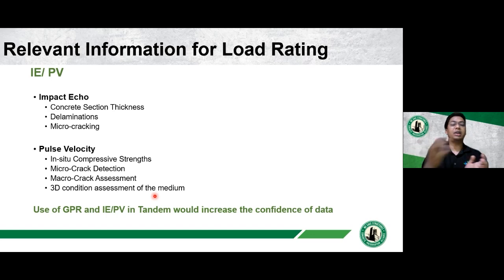Also, 3D condition assessment of the concrete structure in terms of detection of the microcrack or the assessment of the macro cracks. However, I would say that using impact echo in tandem with GPR would increase the confidence in the data. If you use two techniques to assess the structure, it will give you a higher sense of certainty in terms of the data you're looking at.